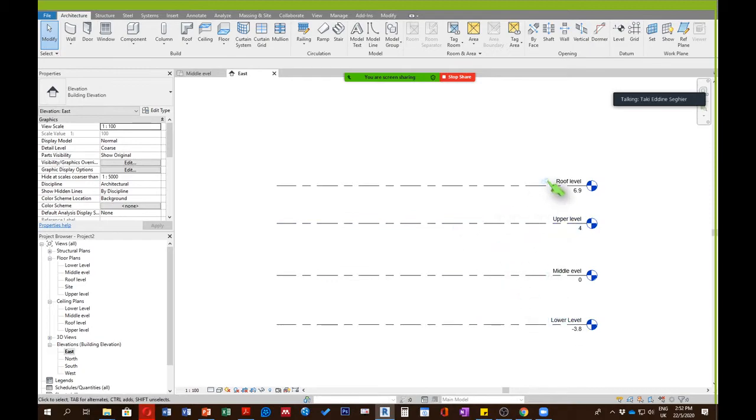Anyway, so we created our levels here. Now, as you can see, they are here automatically. I can see lower, middle, roof and upper. So now, be careful please, you have to go to floor plan, not structural plan, and not ceiling plan. Always be careful to select the floor plan above, because structural plans are used by engineers, but floor plans are used by architects. Here basically we show elements related to the structure, so be careful. We architects or interior architects usually work here in floor plans.